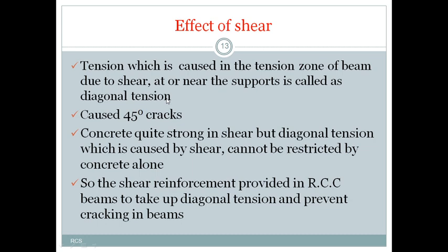Right? The cracks are diagonal. The tension which is caused in the tension zone of a beam due to only shear at or near the support is called diagonal tension.